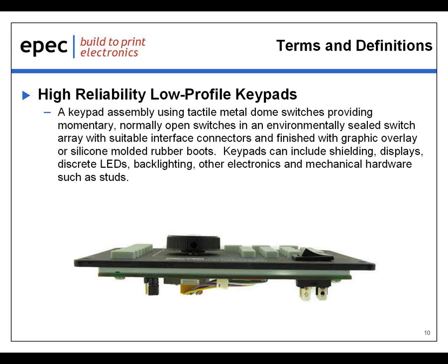High reliability, low profile keypad assemblies use tactile metal dome switches, providing momentary, normally open switches in environmentally sealed switch arrays with suitable interface electronic connectors and finished with graphic overlays or silicon rubber boots. Keypads can include interference shielding, displays, discrete LEDs, backlighting, other electronics, and mechanical hardware such as studs. Keypad assemblies are that. They're assemblies rather than just discrete switches.